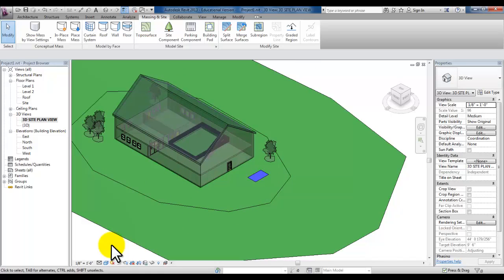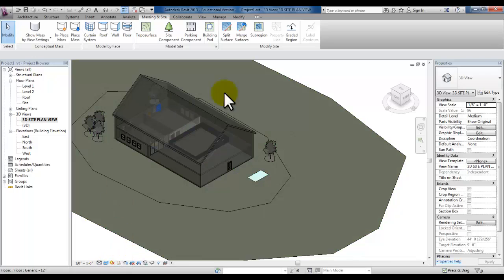Before we render next week, I wanted to show you this visual style called realistic. If you, at the bottom left corner, click here and pick realistic, you'll see that everything is grayed out still. And that's because we're using this transparency.